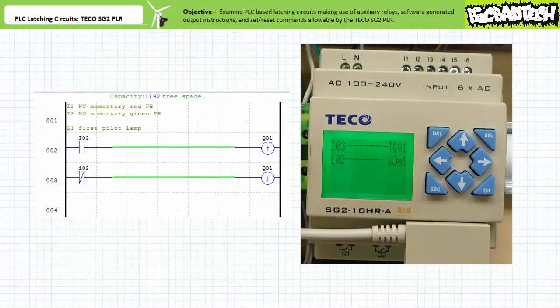When the program is downloaded to a target device, note the subtle formatting differences between the programming software and that employed by the actual device. Note the set and reset commands are respectively upwards and downwards pointing arrows, and the break command examining input I2 in rung 2 is written in lowercase. Not all manufacturers use this particular shorthand notation.